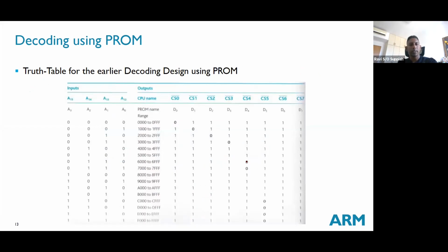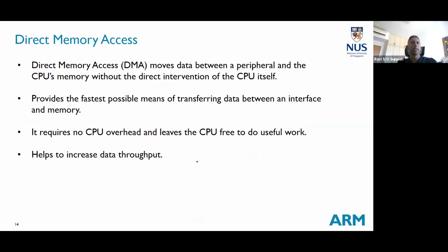Okay, so this is the range. I'm not going to go through this. That basically gives you some idea of address decoding circuitry. And like I said, why it's important is because if you are ever tasked to do something like this, where you have some new peripheral and you are custom building your own board from the processor level up, then you need to be able to design this kind of circuitry to map peripheral devices to different ranges in the address space. So that is why you need to understand how this works.